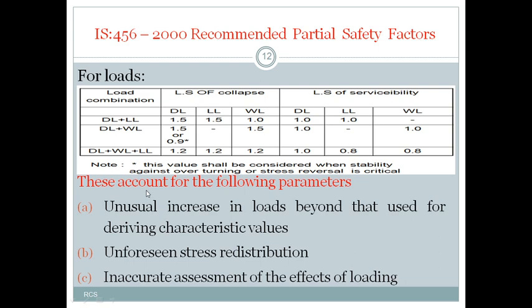And the recommended partial safety factor values for the loads. As I said, we are using a combination of loads. We cannot use a single load. We cannot design the structure by considering dead load alone, because we may have some live loads on it. We may have the wind effect on that particular structure. We may have some earthquake loads, or we may be constructing the structure in a snowfall area.